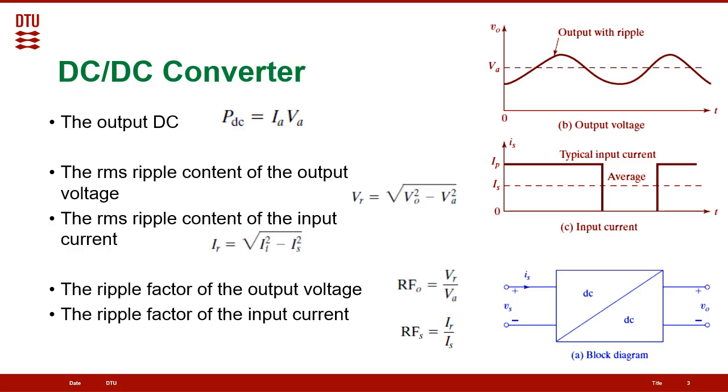If we have any DC signal, what the converter is doing is based on chopping. If we just switch on, switch off, we are actually switching or chopping the input signal. As we can see in this square wave, the output voltage will be just the average of this signal.